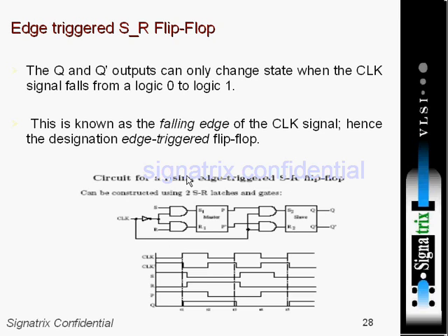Circuit for a rising edge triggered SR flip-flop, which can be constructed using two SR latches and gates, as seen here. The clock input is going in inverted for the first SR latch, and then the clock pulse is going for the second SR latch here, and then at the end we attain the outputs in the form of Q and Q dash. So this is the working